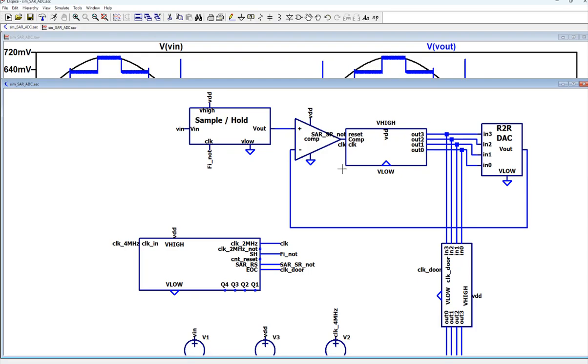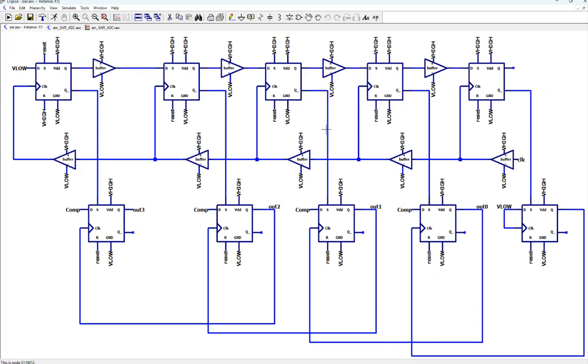To where? Yeah, it's to S. So that 0 will set or reset. Will set, right? Because it's shorted to S. So that 0 will set the first one and output a what over here? 1. But all the following ones are zeros. So you are getting 1, 0, 0, all zeros as the first output by doing that reset, right? And that reset should happen right after the falling edge of the sample and hold pulse. Gotcha. So you want to give a 0 to that first S in order to load 1 0 0 0 0. Yes.